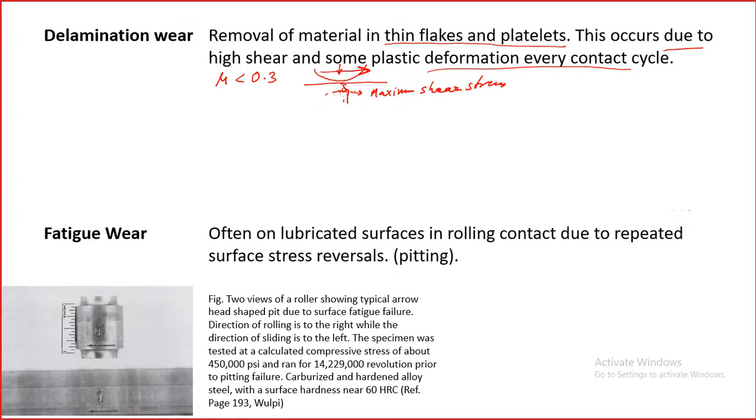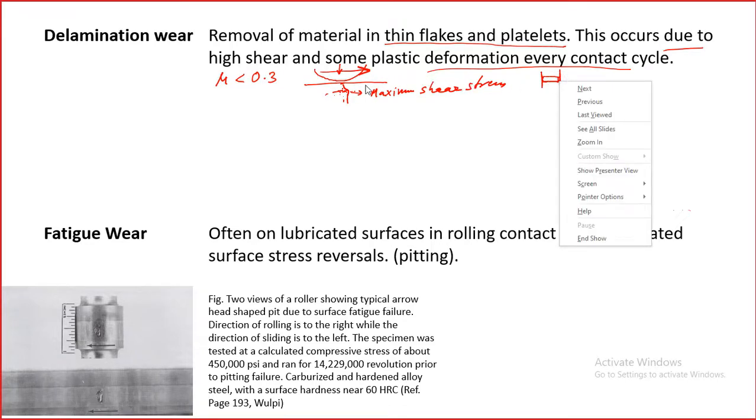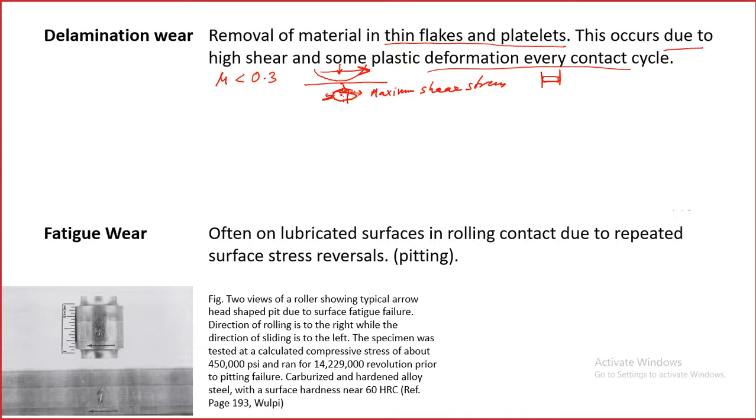surface comes in contact. So for example, if you imagine an IC engine, for example cylinder and piston, at every point, any given point, there will be repeated sliding, okay, and because of this repeated sliding the plastic deformation continues to happen, but at some point the material at this point will be completely strain hardened and ductility will be reduced.